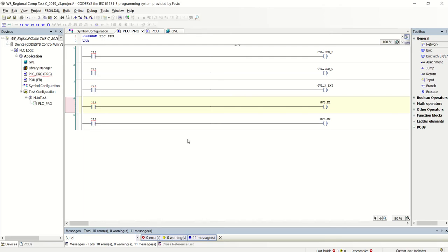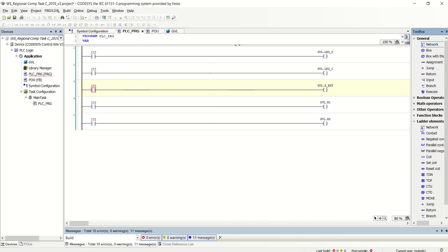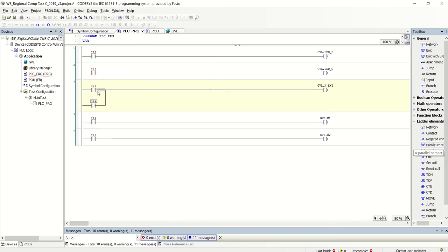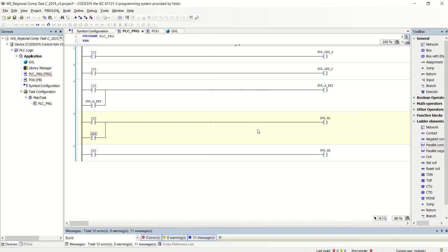So when I keep that in mind, I will just spot that early, and I will bring in my latch just so that I have that going from the start. So I know I'm going to need to latch this on. And then I also know from my LEDs, they're going to need to latch on, because if I just pulse my LEDs, well, I'll never actually see them coming on.